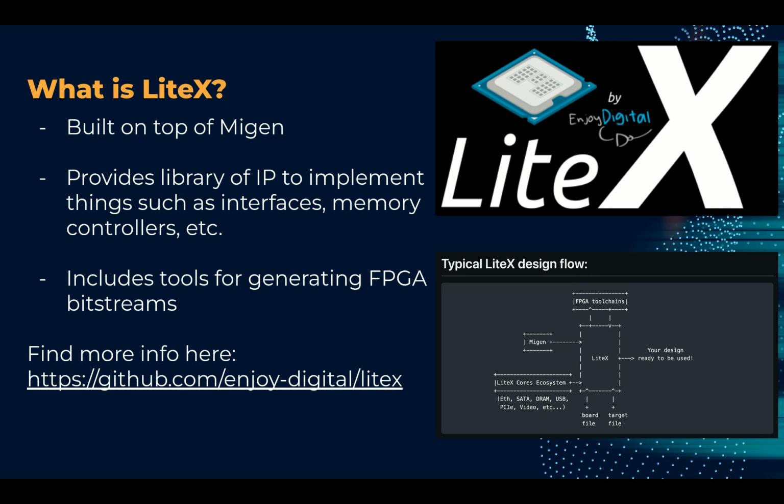And these can be customized and combined to create an SoC that can meet the specific requirements of your project. Also included in LiteX are tools for generating bitstreams for FPGAs and simulating designs using a hardware simulator. What this means is it makes it easy to test and debug designs before actually implementing them into hardware. So overall, it's a powerful, flexible platform for designing these SoCs, and it's very widely used now.